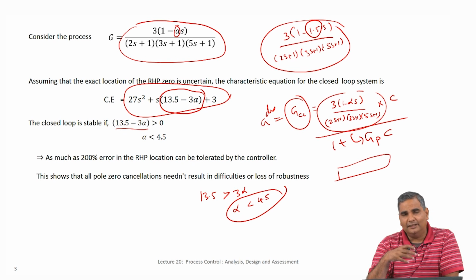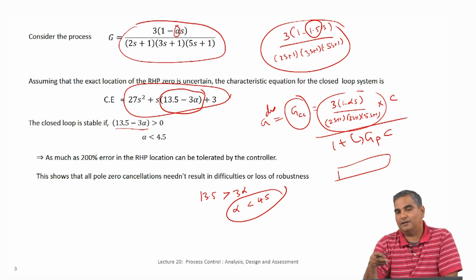While this is a little more explicit than your Ziegler-Nichols tuning, it is not used in online controller computations. I mean the model is not being used online. But in the next topic, which is how do you control time delay systems, you will see that the use of the model will be more explicit even in the controller calculation. You cannot simply live with the PID, but on top of a PID there are some model related terms that come into the online controller computations. So, without the model you cannot implement the controller. In the other case, once the controller is designed, you can directly implement it.